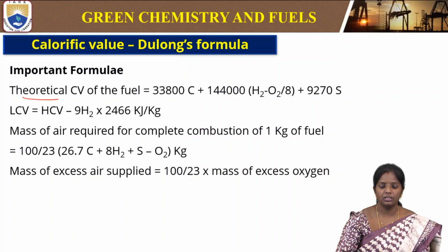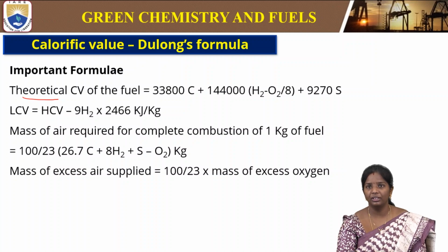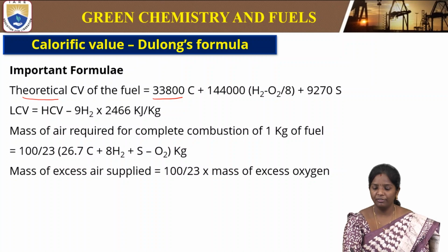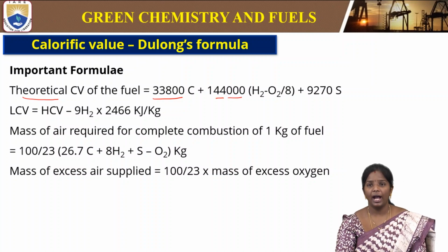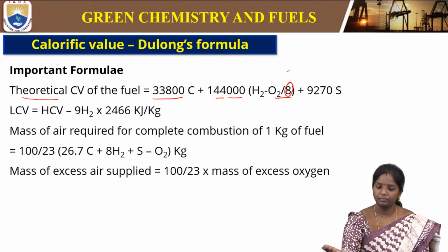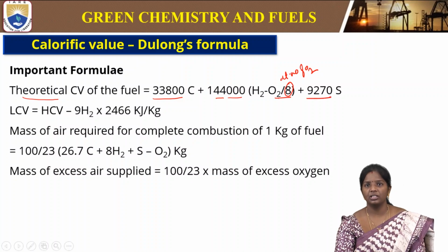The theoretical calorific value of the fuel is equal to 33800 carbon plus 144,000 into hydrogen minus oxygen by 8, plus 9270 sulfur.